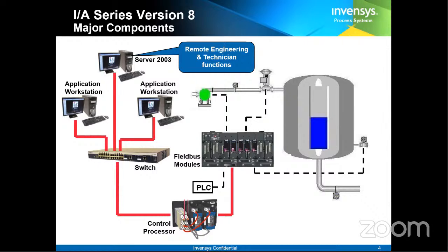If you are providing the output to a pump, simply to make it on or off, then you will have a digital output module. Next, we also have basic analog input and analog output modules. In the case of an analog input module, the field transmitter will provide the signal in a range of 4 to 20 milliampere. The analog input module will convert this 4 to 20 milliampere into some count, which is just a range of data values in digital form. Those counts vary from system to system.